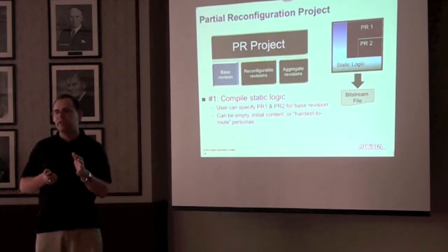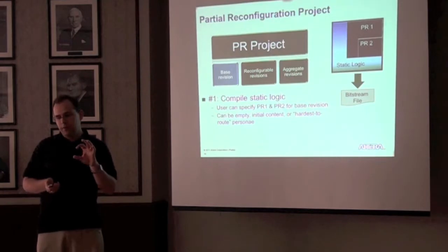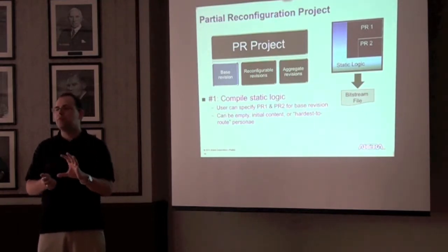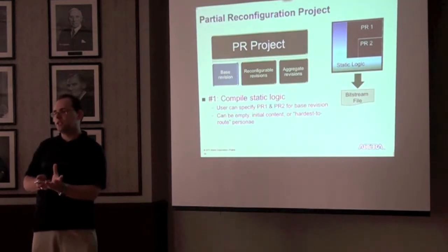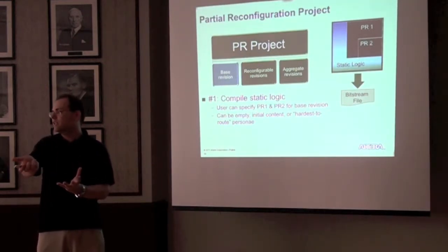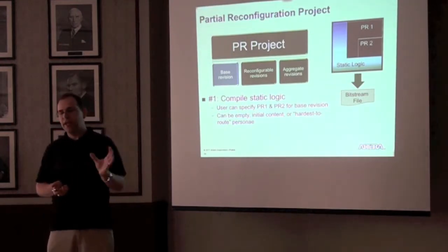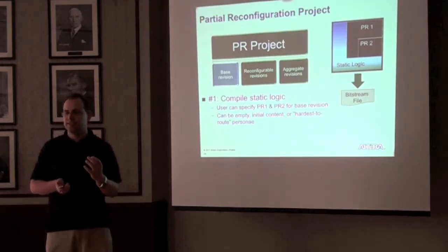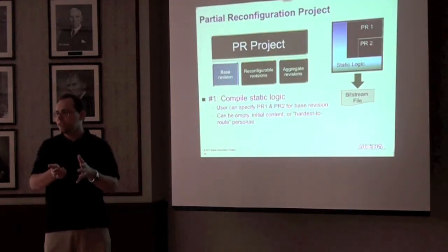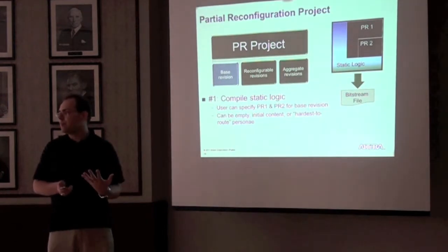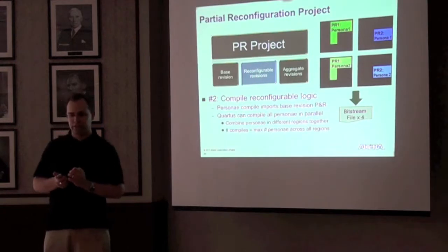They can specify it with the initial content that they want programmed onto the device, or you can specify the hardest to route persona, because there is some interaction in the software of how the static logic is compiled depending on the content of the other chip. And that will become more apparent later. So the output of this compile is a bitstream file, which of course is the one going to be loaded into the chip initially, and also some internal databases that will be used to compile the later revisions,